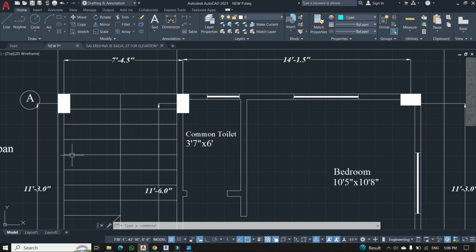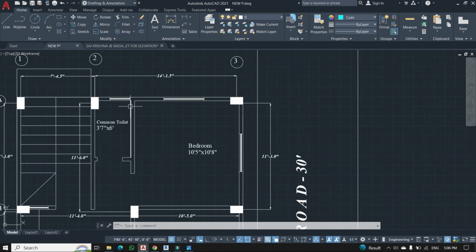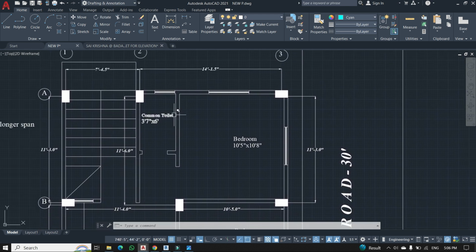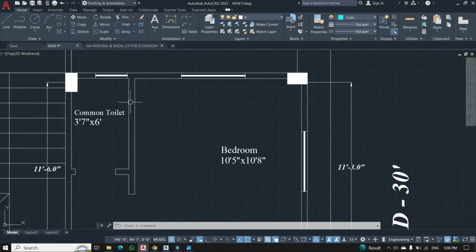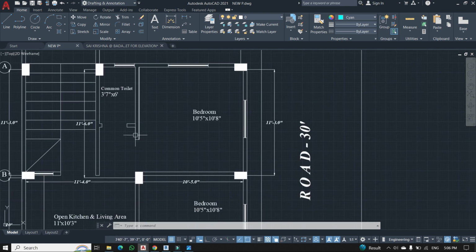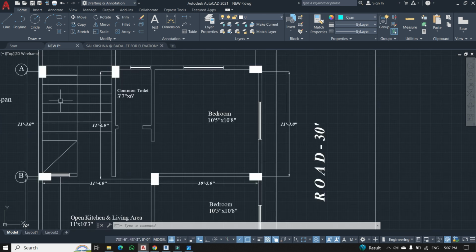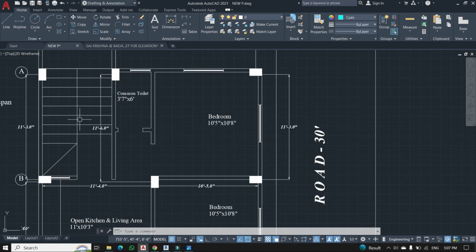तो यहाँ पे भी जहां जहां walls हैं वहां पे you are supposed to place the columns. It doesn't mean that wherever the walls are there, you will place columns. At some places, this is a shorter wall. No need of placing a column over here. This is a longer span wall and here I am having even the staircase. तो यहाँ पे place करना जरूरी है. Okay. So it comes by experience.